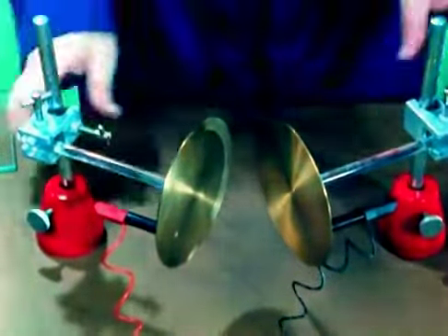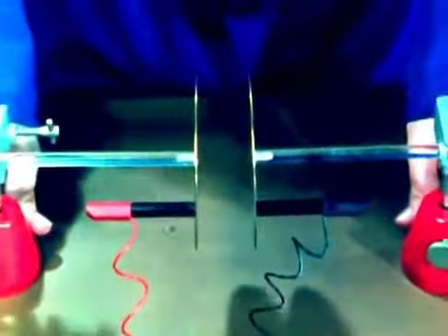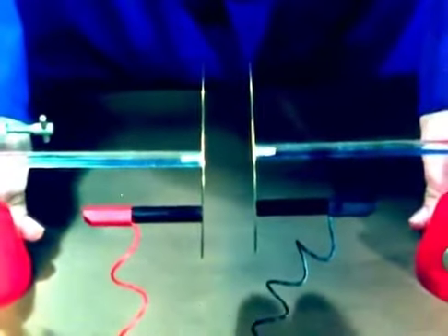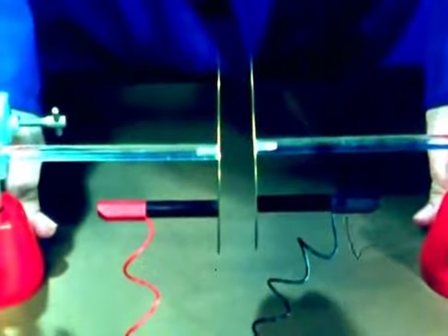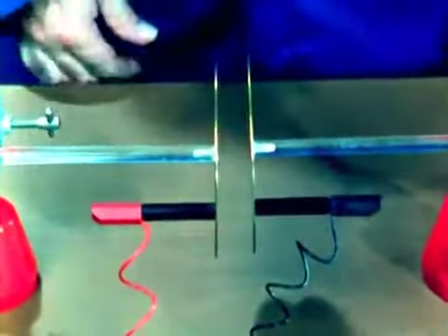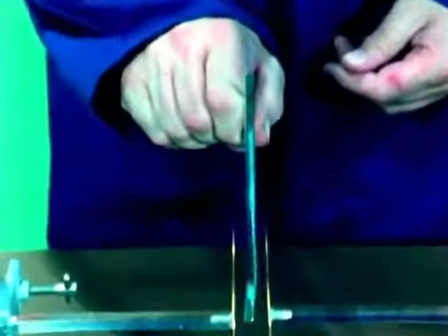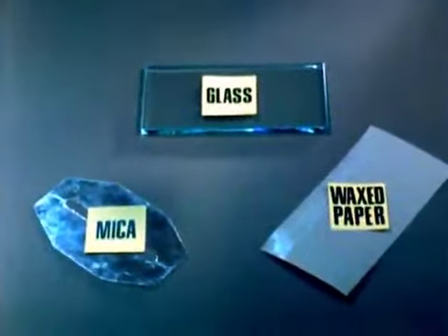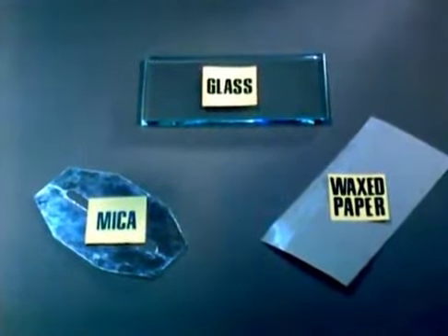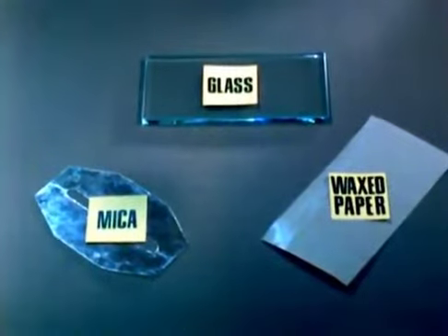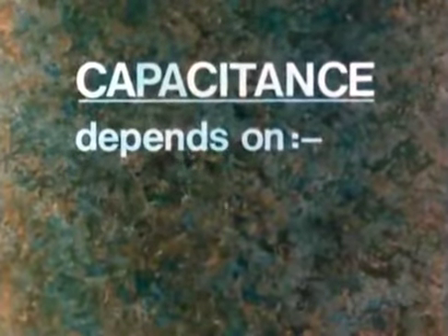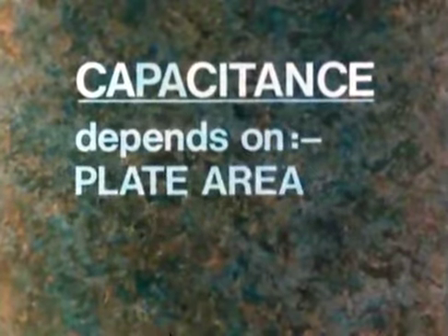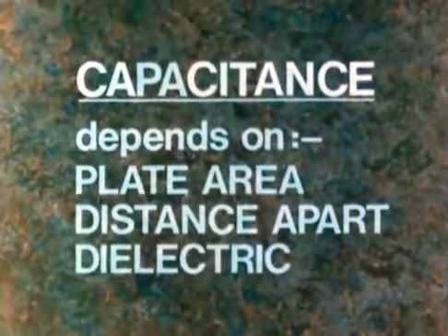Next, the distance between the plates affects capacitance. The closer they are together, the greater the capacitance. And finally, the dielectric. Here it's air, but if a better dielectric is used, more charge could be stored. The capacitance would be greater. Typical dielectric materials in addition to air are mica, glass, and waxed paper. So the ability of a capacitor to store charge, its capacitance, depends on the area of the plates, the distance they're apart, and the dielectric between them.